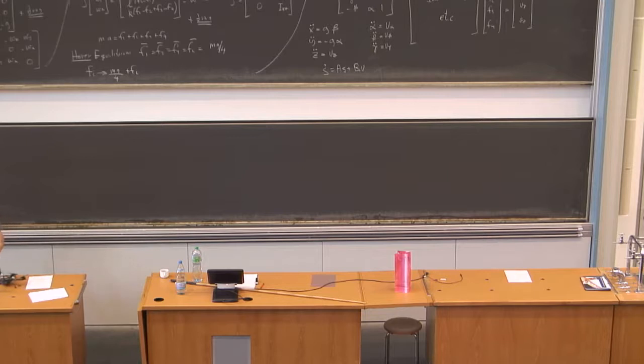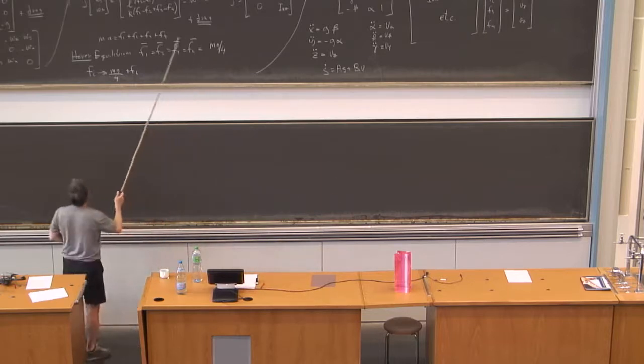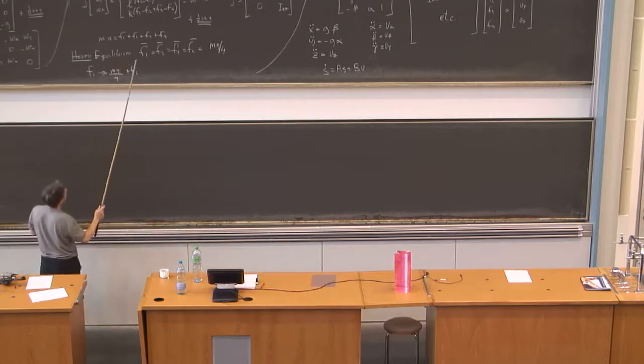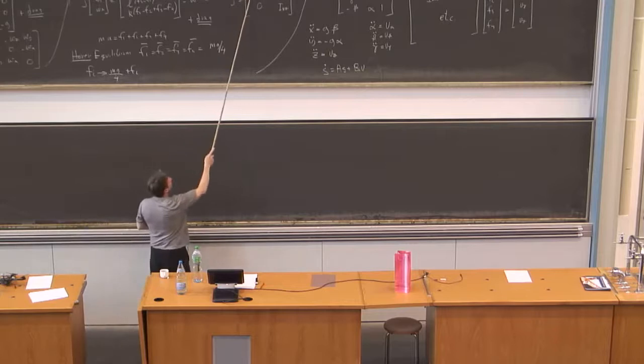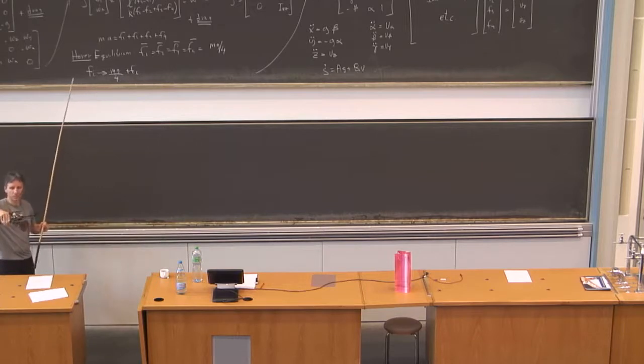Now I'm going to talk about some assumptions. I'm going to assume, again, a reasonable assumption for a quadcopter, and this just simplifies the analysis, that Ixx is equal to Iyy. So there's symmetry in this quadcopter. It's a pretty good assumption. I mean, the battery is not exactly where, it's not an exact relationship, but it's close enough for this analysis.